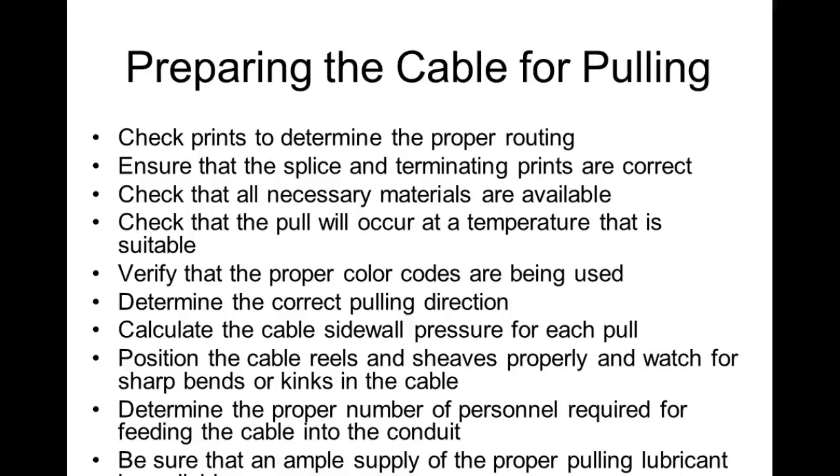Determine the proper number of personnel required for feeding the cable into the conduit. Be sure that there is an ample supply of pulling lubricant. And I can't see what it says at the bottom. So pulling lubricant is just something that we smear on the cable while it's being pulled to reduce friction, right? Are you okay?